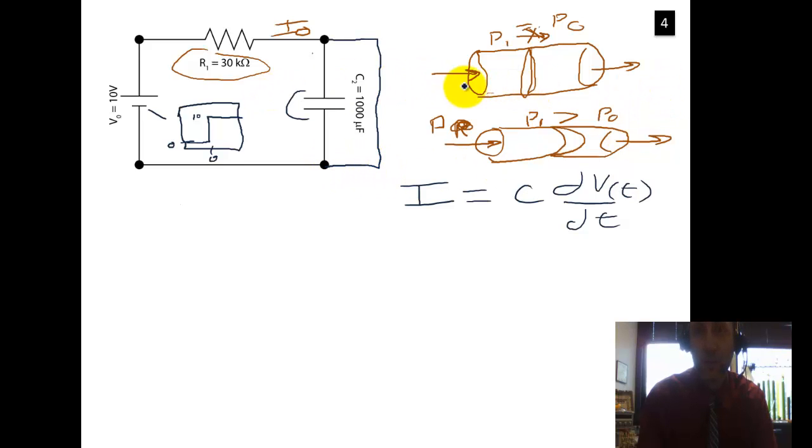Like if this was a hydraulic system and we turned on a pump, this diaphragm isn't stretched at all, so the first little bit of water can push on it as though it's not even there and move into this chamber and push out liquid from this chamber, and it's as though this is just a pipe. But as time goes on, this diaphragm is not going to stretch infinitely. It's going to keep pushing back more and more as the pressure builds up in here, but it's never going to let liquid flow through.